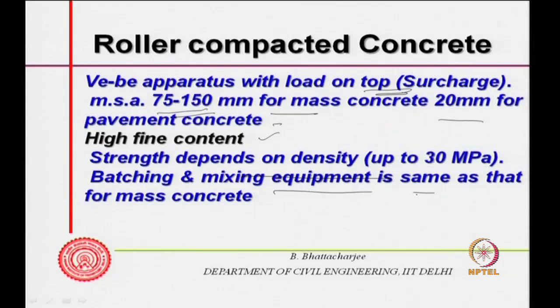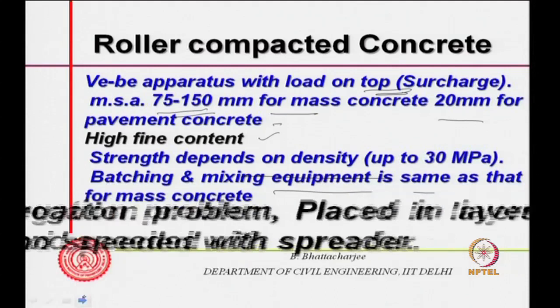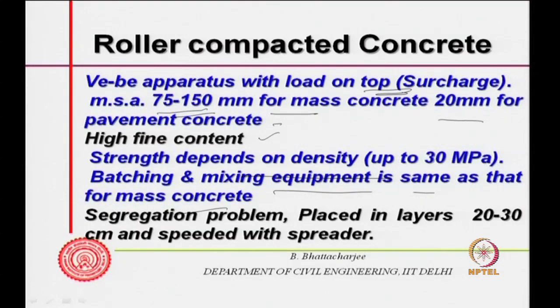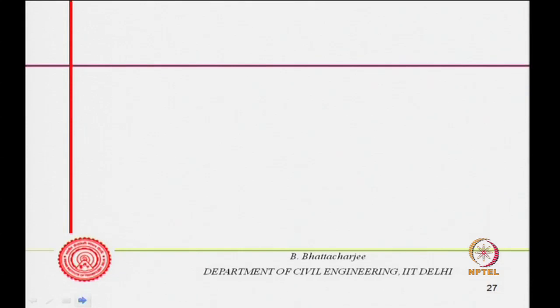Batching and mixing is the same as that of normal concrete, or mass concrete, and then the segregation problem is there if you are taking it by truck. It is placed in layers of 20 to 30 centimeter and spread with spreaders.